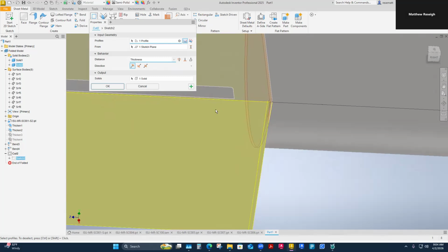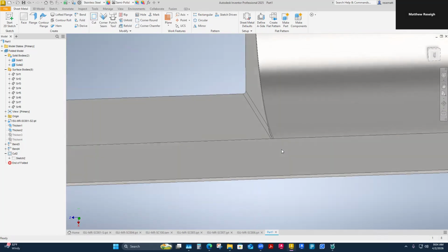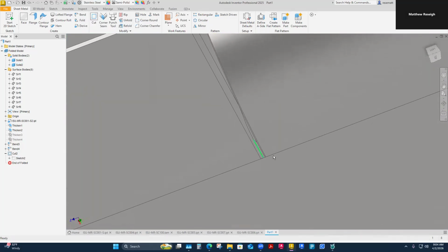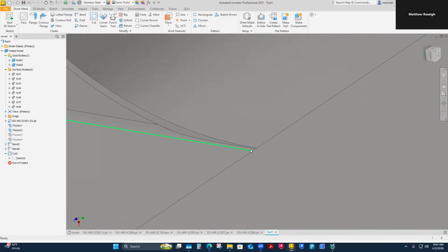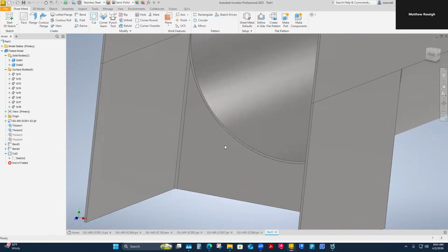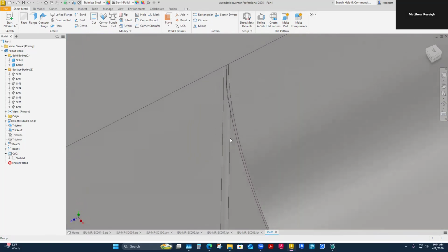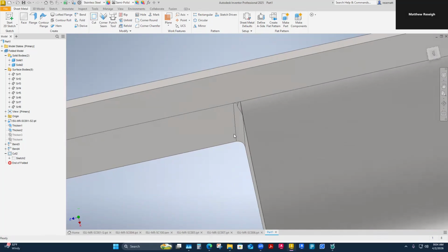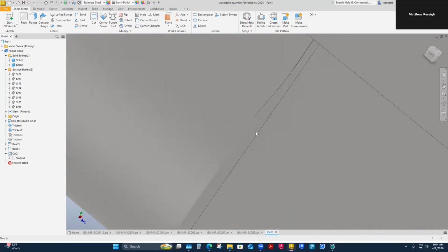But this I was kind of happier with. Whether you do a little bit more or less to cut that out, I'm going to leave mine just with thickness cut with a little bit of the bend remnant here. I'm going to go look at the part individually and see how the flat pattern looks on it now. I did plus 30 thousandths. Whether that was good or bad, I kind of went back to not the 30 thousandths.